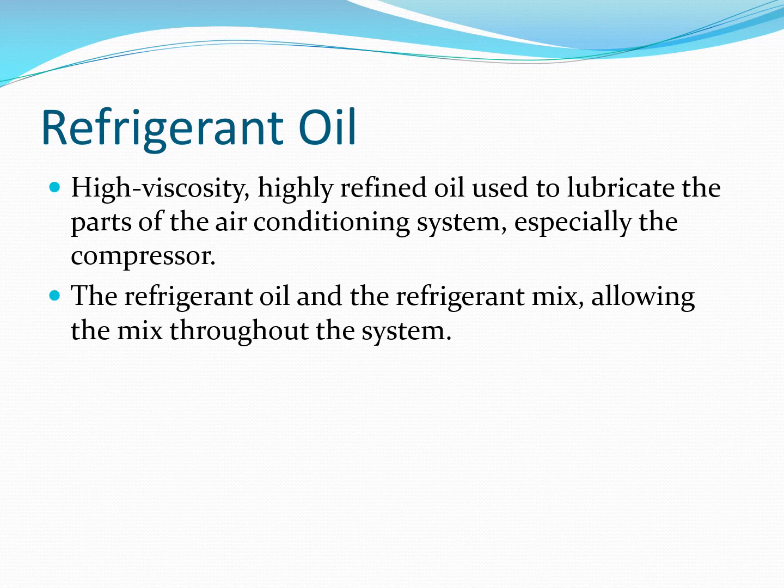So using the correct oil to lubricate that $300, $400, $500 air conditioner compressor is essential. You as a technician could very well put the wrong refrigerant oil into a system and burn up a brand new compressor. That would not be a good situation. On the engine bay should be a sticker somewhere that tells you how much refrigerant the system holds and what